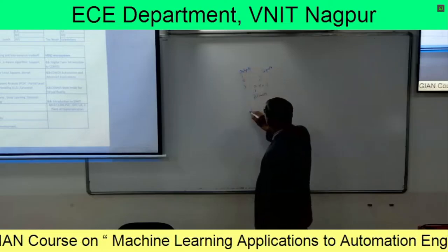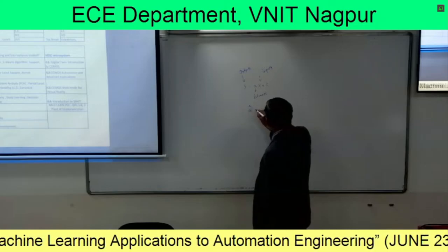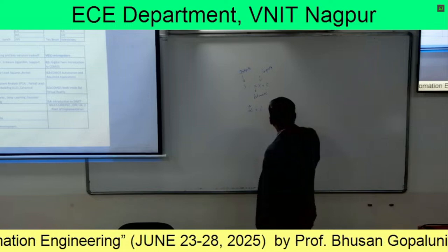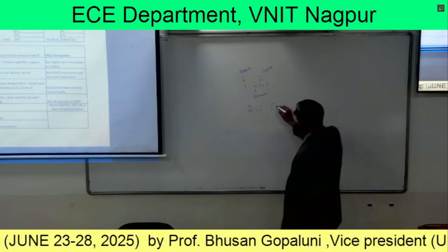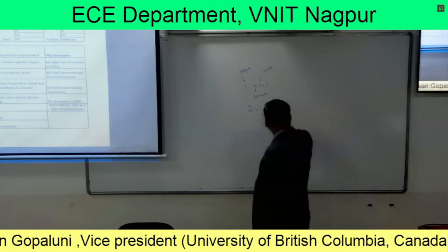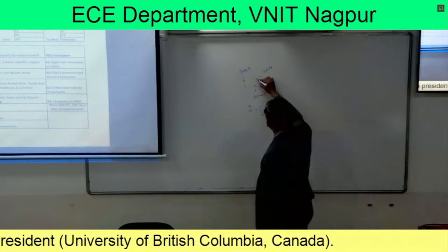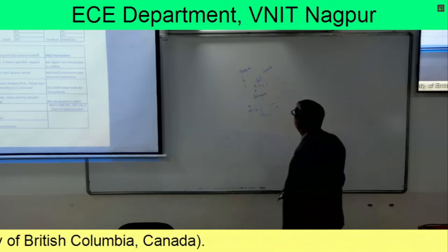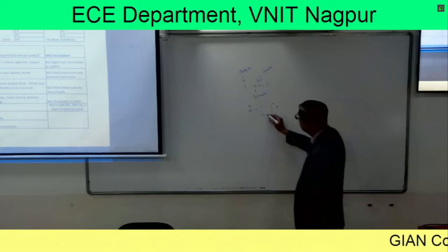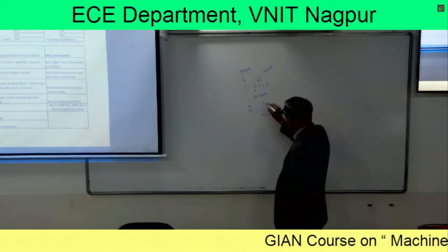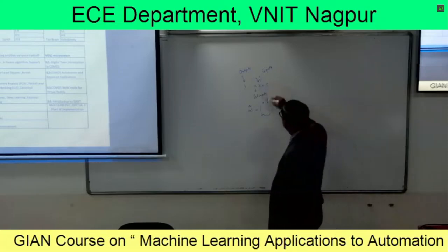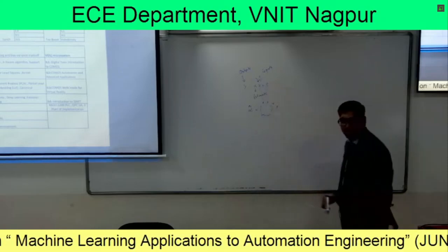So you can solve this using least squares. You get an estimate of alpha, where you find the pseudo-inverse of some matrix times y. Right? Now, if this matrix has to be invertible, then you have to choose your inputs appropriately. Right? So this matrix is going to have x and y in it. Okay? So you have to choose your inputs in such a way that this matrix is invertible.